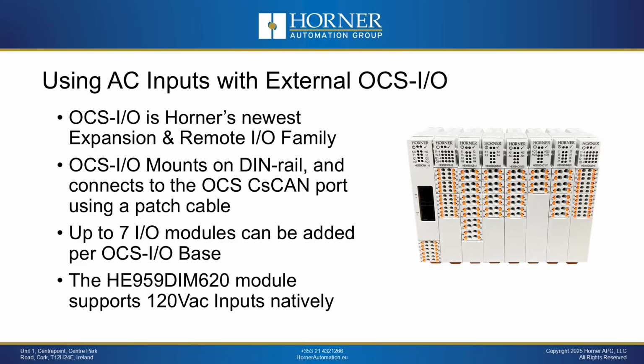One base strictly provides a connection to your OCS with no built-in I/O of its own, and the other base component offers not only the connection back to OCS but also built-in I/O. Once you have started with your base component, you can add up to 7 extra I/O modules per base, and you can have up to 16 bases per system.